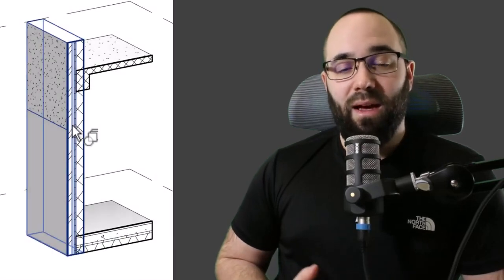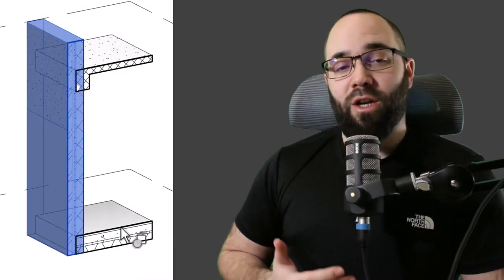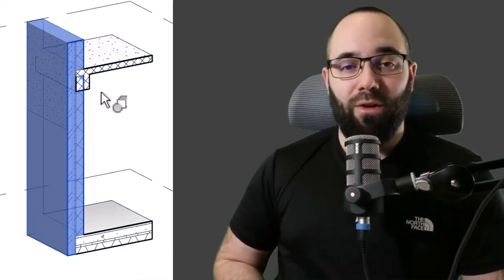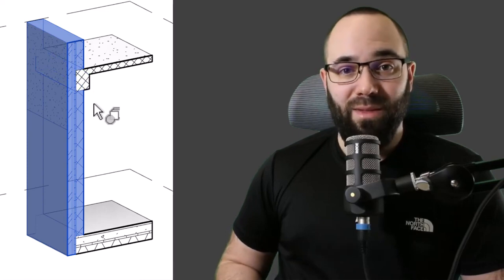In this video, I'm going to be showing you how to avoid a very common mistake with overlapping geometry in Revit. That means that you have basically counted geometry twice in the same spot, and then you would get schedules with too much material that then gets ordered to the building site, and then you're left with a lot of unused material that you have paid for. So any mistake that costs money is very bad, so we're going to learn how to avoid it.